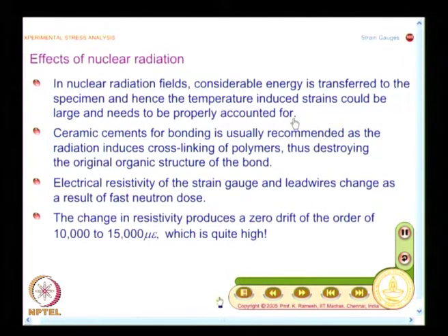See, we have earlier looked at how to accommodate small temperature changes. Here it does not come under the small temperature changes category, you have large temperature changes possible, and on those occasions the recommendation is measure the temperature at the point of interest. With that data, it is possible for you to go and do some corrective modifications on the strain measured.